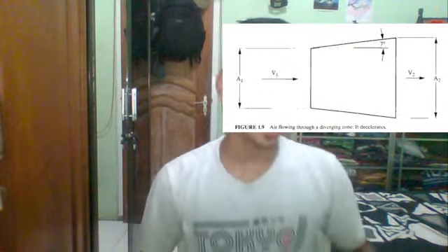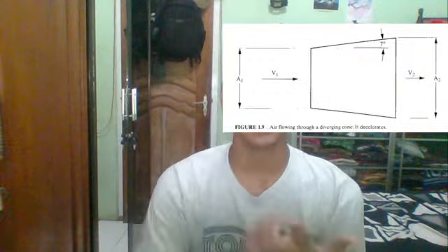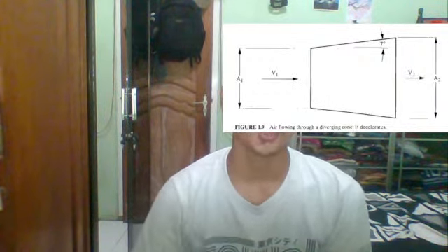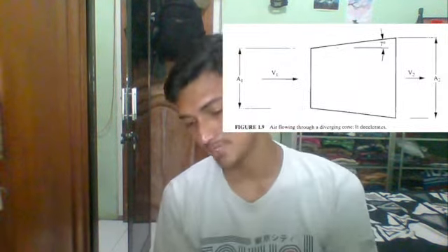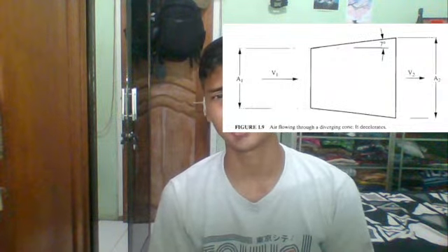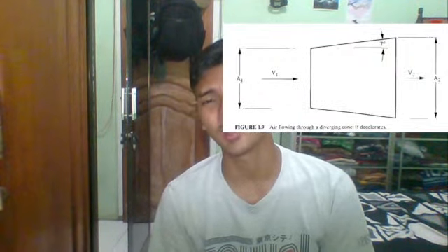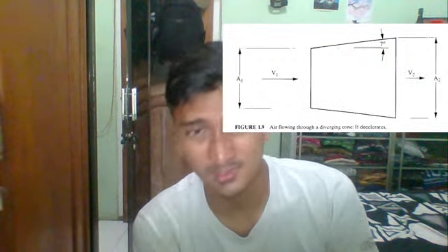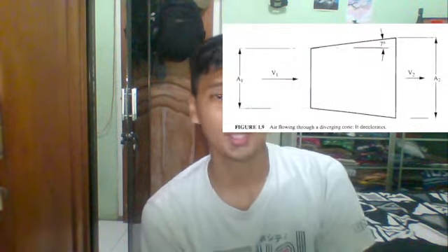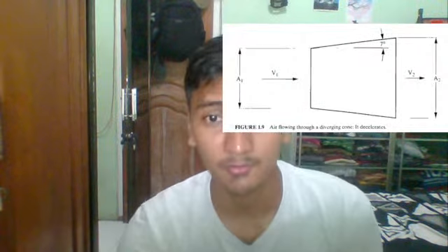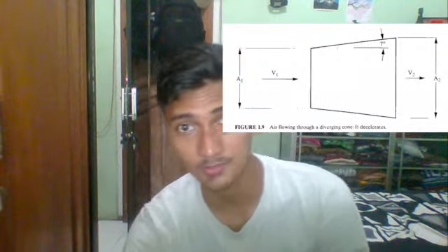After we know about that converging, diverging, and Bernoulli theorem, I have to show you this paradox. I read it maybe 2 weeks ago. I wrote about the aerodynamic paradox. Normally, as we go along with airflow through the duct system, the static pressure is highest upstream and gradually decreases from there, right?